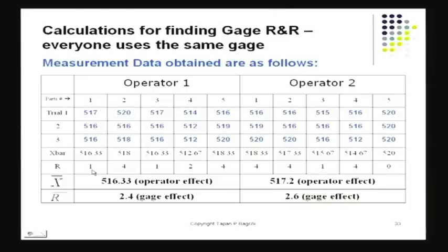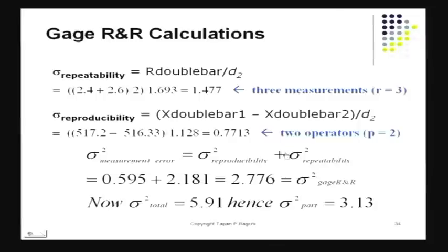When I calculated from R, my R calculation came from the variation of these 3 gauges there, and that's what I've got there. If I go back to the calculation again, these 3 measurements led to my estimate of sigma repeatability. That's the standard deviation of repeatability.